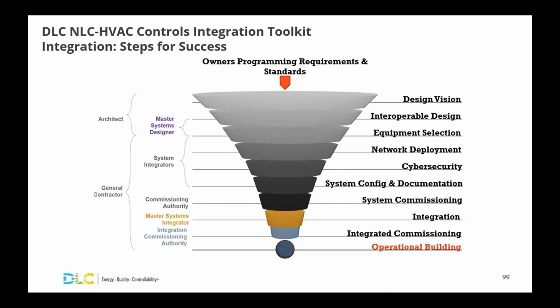So if you've seen traditional delivery of HVAC or lighting, you traditionally have a commissioning agent. They're going to come out. They're going to check it. They're going to make sure it functions right. Well, what happens when you then need to do an integration? If you're sharing data between the various systems, you can have that system programmed and finished potentially, but you haven't necessarily programmed the other system, which is going to consume the data outside of it. So what's going to happen with that? Well, what you can do with this framework is you can help define the activities that need to happen for that integration to occur, right?